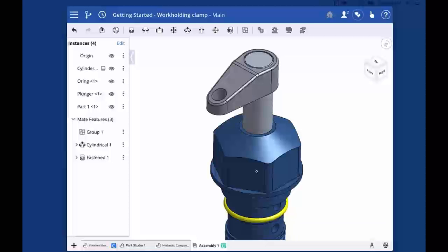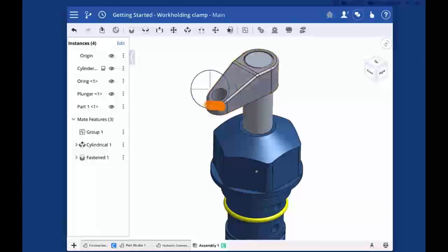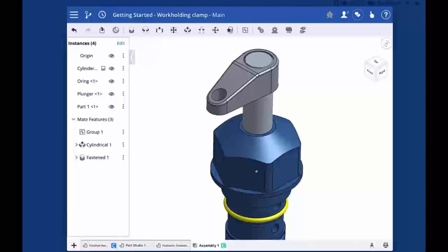Okay, so that's really what I had planned for you here today. Now, the big things that I want to point out, things like the two-finger tap context menu, the single finger tap and hold precision selector that allows you to highlight very precisely, double tapping to deselect. Those are the key things. If I had to make a list of three or four things to take away from this, those would be the key things. They're going to make a huge difference in how efficient you are and how you can get around inside the Onshape app.